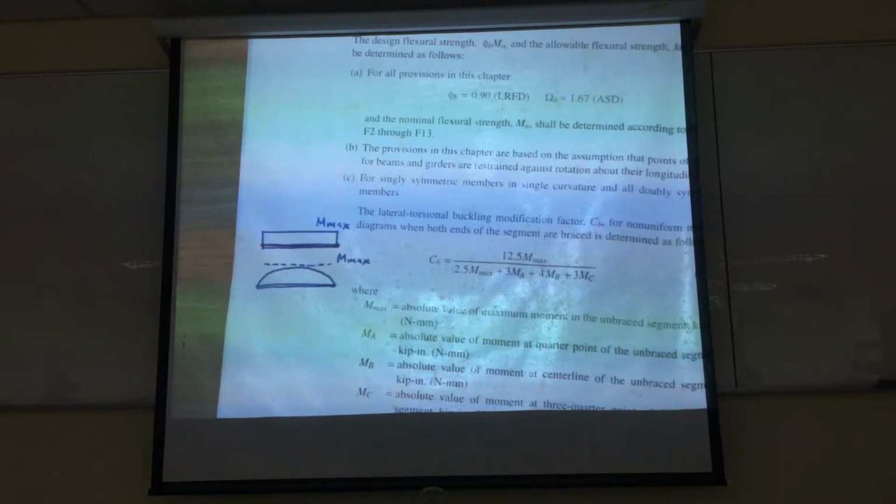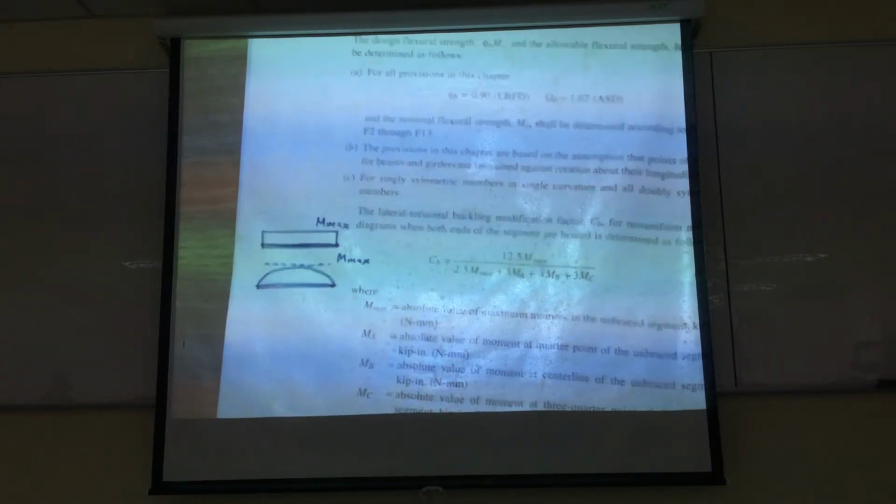If you divide the 10,000 by 18, not including the columns, you get how much? 500 baht, probably, per beam. Your life is so cheap, eh? So as it is so cheap, you have B1 and B2 for the whole house. You'll have quite a very overstrength beam in many places, but okay, that's the deal. You just don't want to design too many members.